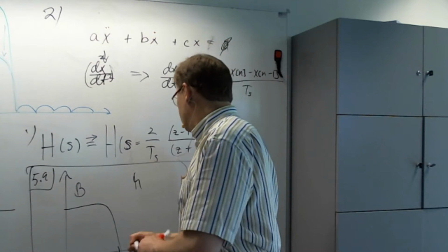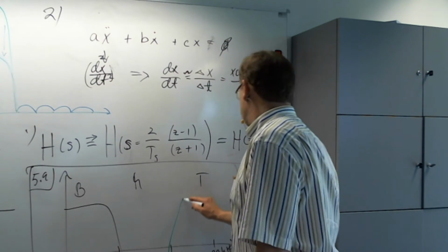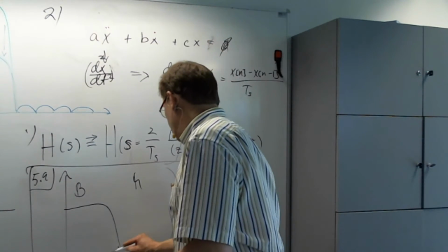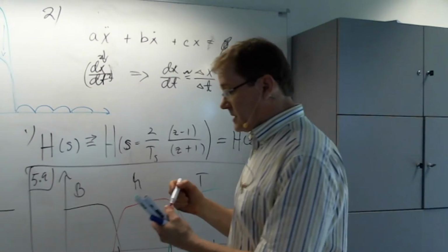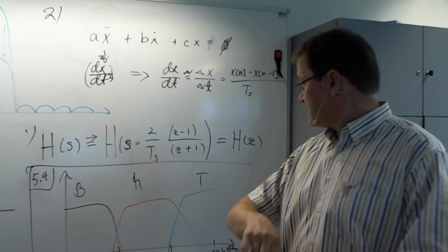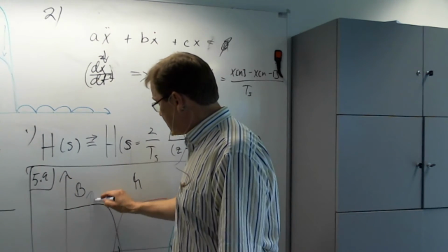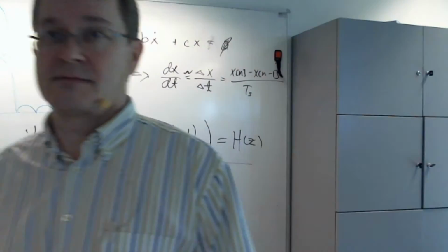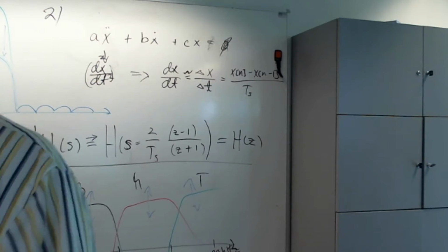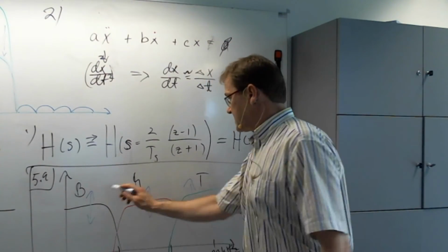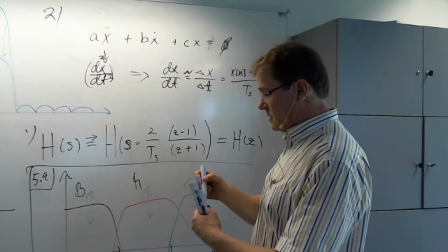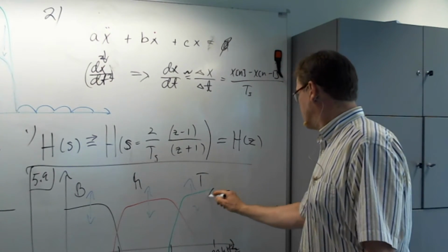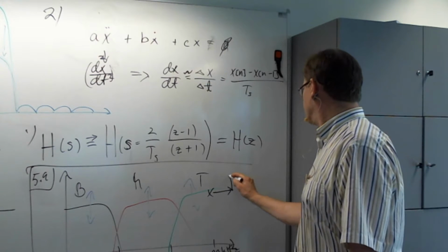The bass filter is a low pass filter, the treble or discant is the high pass filter, and the band pass is for the middle. The tone adjustment is very simple. You just add some gain to those bands and mix. So basically the system looks like this.